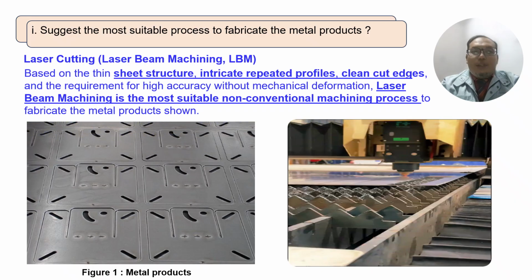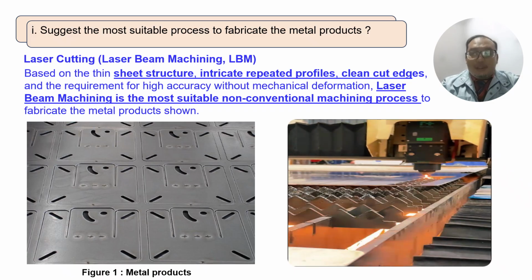Based on the thin sheet structure, intricate repeated profile, and clean cut edges, laser beam machining is the most suitable non-conventional machining process to perform cutting on this kind of metal sheet. Here, I also attach a video showing how laser beam machining cuts the metal sheet.